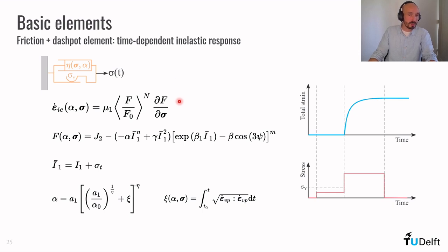Okay, now let's talk about the yield function, because the yield function is actually the threshold that I was talking about a bit earlier. This threshold here is not actually a number, but a function or a surface. So this yield function is calculated based on alpha and the stress. Once we have the stress, we can compute J2, I1.